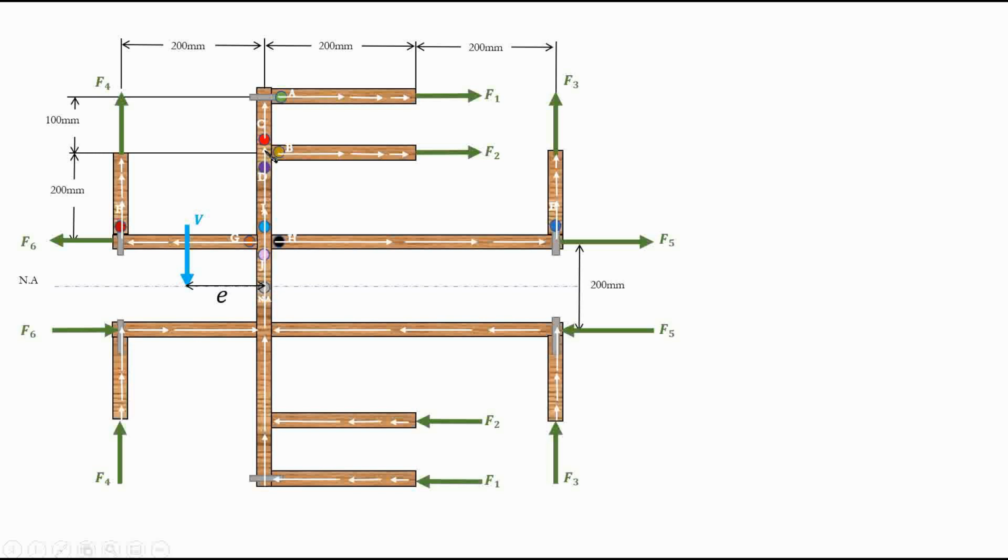So what would be the moment resulting from this force? 0, right? Because the distance is 0. So this force would not create any moment. That's why we were calculating the moment about this point in specific, right? It's easier to take it about this point, or of course any point in the web.